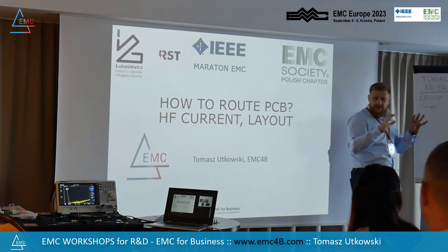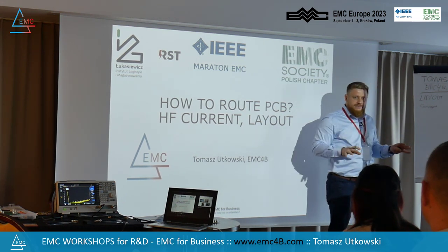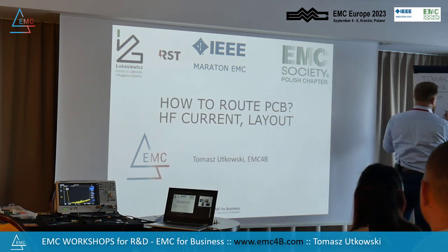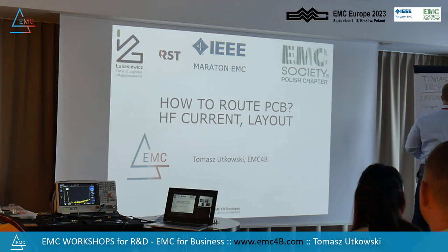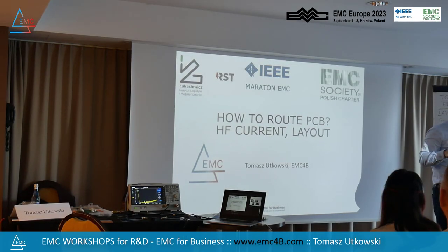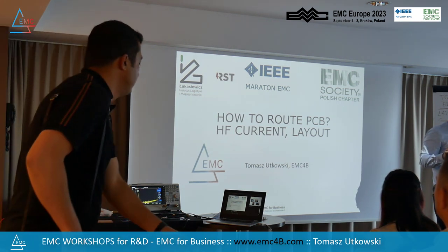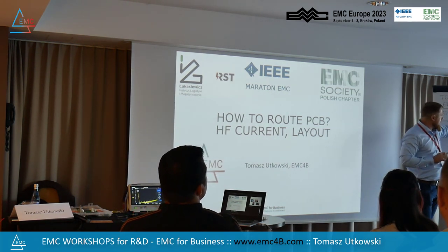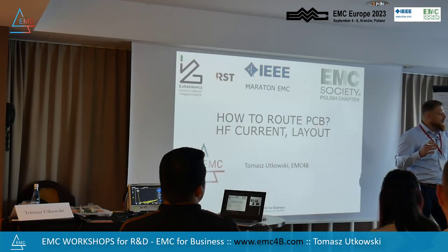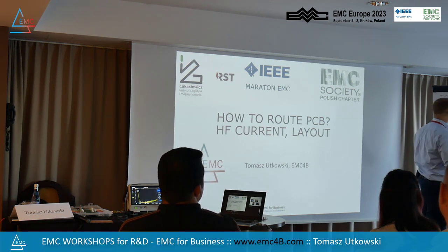We've got some concept. Okay, this device should have this kind of interfaces. Then we've got a block diagram and schematic. At this stage, we also need to consider some EMC problems, yes? So what do we do during schematic time? Predict disturbances, and then what? Apply some filters. Place some filters.